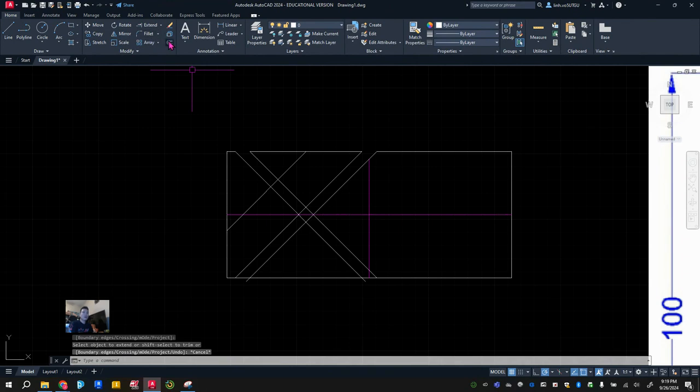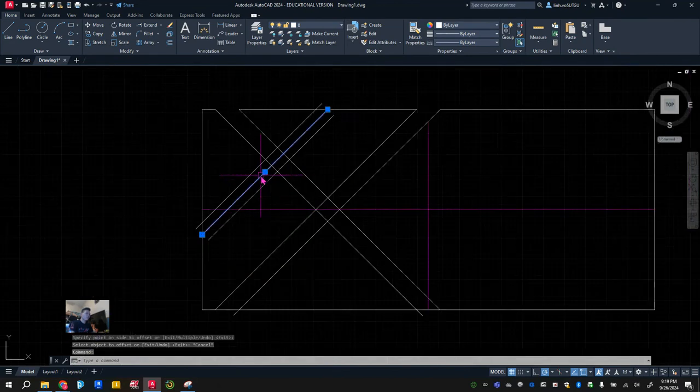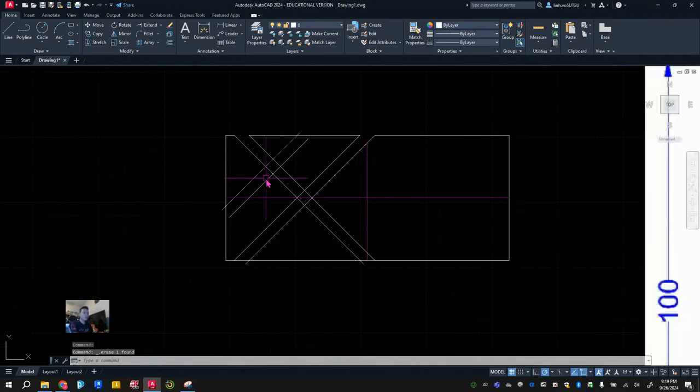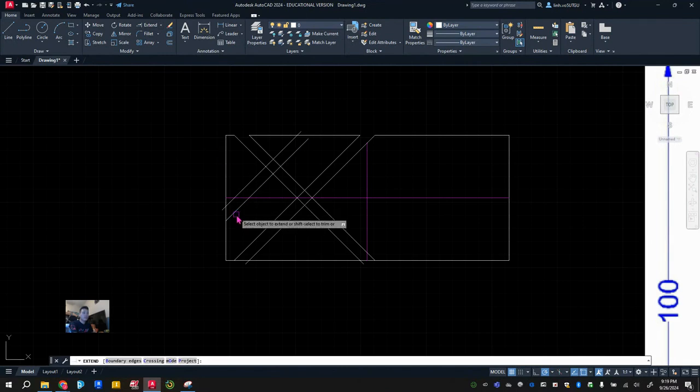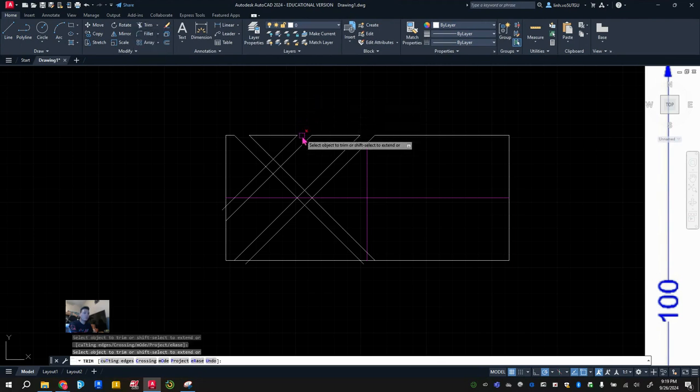Again, you can just go to extend and extend it out. Offset is 1 unit. It's already there, 1 up, 1 down. All right, we have those. Escape. Get rid of the original line that we created. We're going to keep the offset one. Extend that, extend that. Okay. And then we can go there and we can trim. Now at this point, after I trim, you guys can see that we will see some dimension. I'm going to trim.